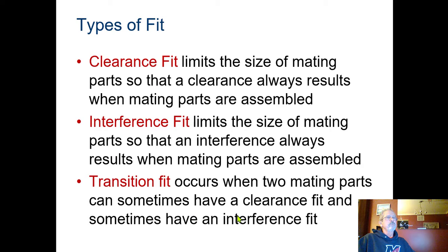All right, so there are different types of fit. Now, there is a clearance fit, an interference fit, and a transition fit. Well, what does that mean? Well, I want you to think about your Tonka truck or your Barbie or Ken Safari Jeep and how the wheels are put on the axle on those. Okay, they are squeezed on. Now, that's an interference fit. When they get squeezed on like that, that's an interference fit. There always should be an interference fit for them to stick together and to hold on together.